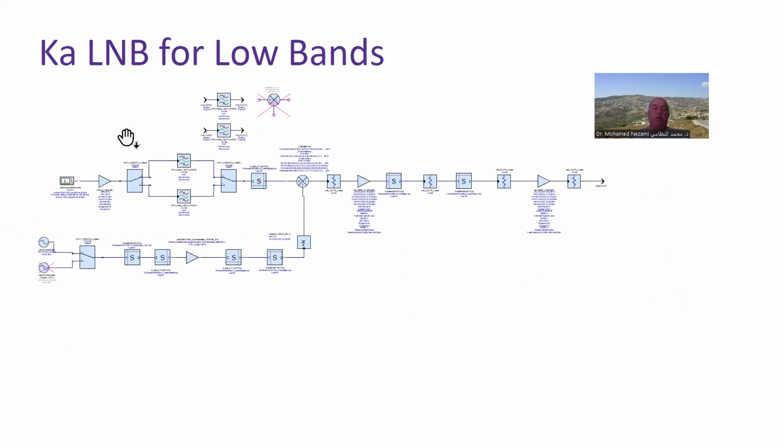So I have this built up, constructed, all the models scooped into the system. In the system, the low band goes from here through this filter, out to this common IF, and then the LO is going to be switched. So this is the low band LO, and the low band LO has the value 8.125, where the upper band is 9.125 gigahertz.